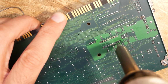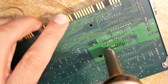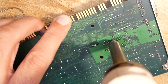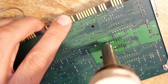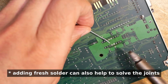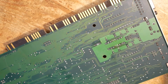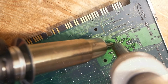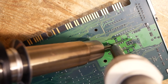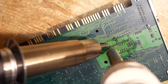Pay attention to the middle 4 pins of the IC. They are all ground and the IC is not socketed. The amplifier can get hot when working, and as you can see, there is a bigger ground plane underneath which is used as a heat spreader. That's why the middle pins are used to transfer the heat to the ground plane. This makes it complicated to desolder the IC. The solder pump is not able to fight against the heat dissipation of the ground plane.